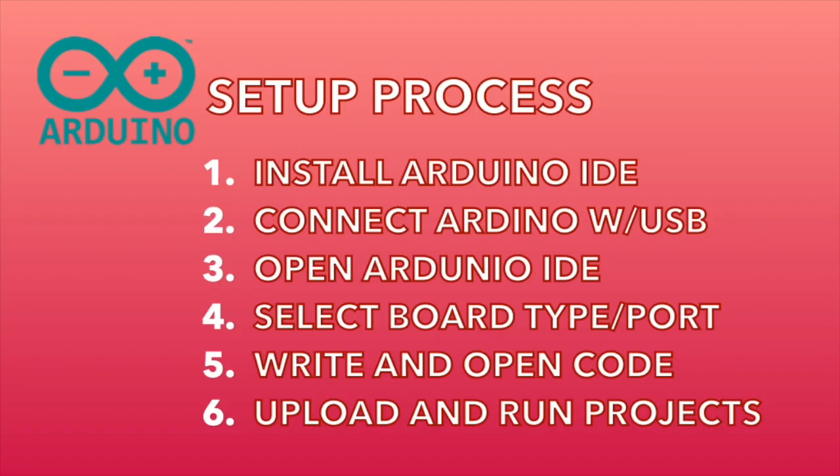After that, open the Arduino IDE. In the software, go to the Tools menu and select the correct board type, such as Arduino Uno. Then select the correct port so the computer can detect the board. Now you can write or open a sample code, a sketch, in the IDE.